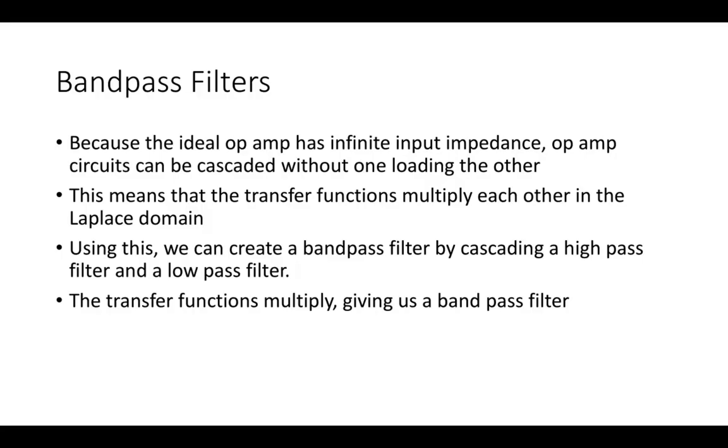Okay, in this part of the Introduction to Active Filters lectures, we're going to discuss bandpass and band reject filters. First let me say that the bandpass filter, because it has two cutoff frequencies, an upper and a lower, and same with the band reject, they're actually considered second order filters because you'll find in the denominator of the transfer function we have a quadratic.